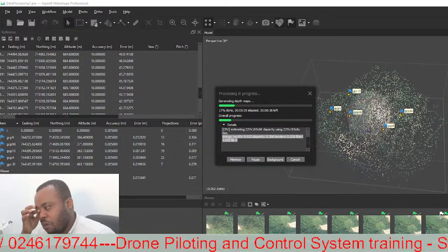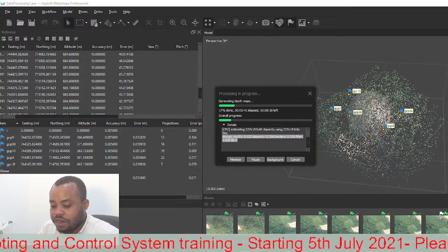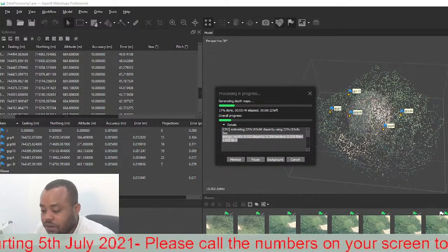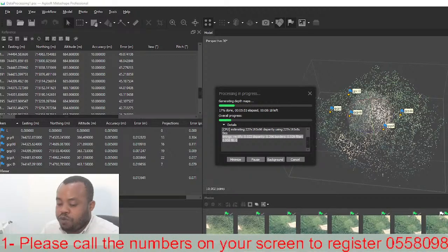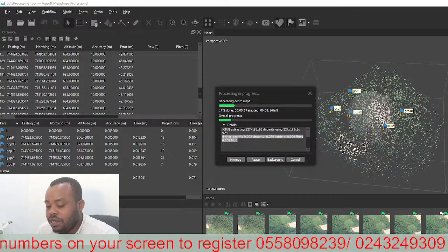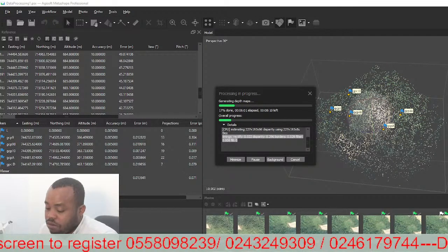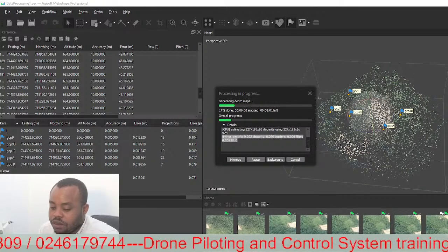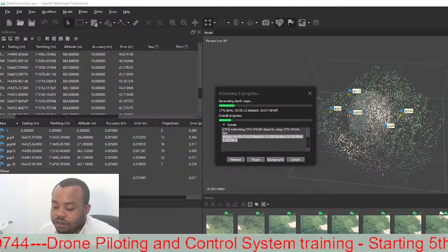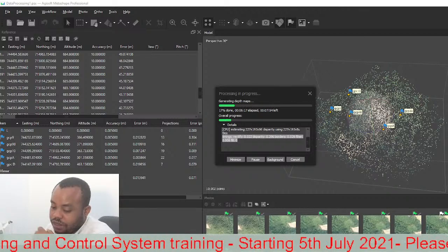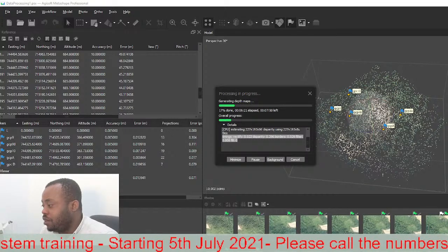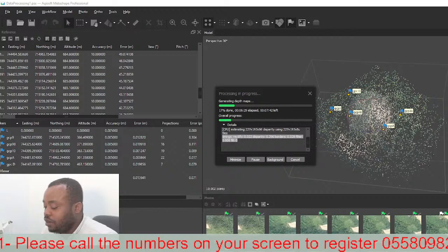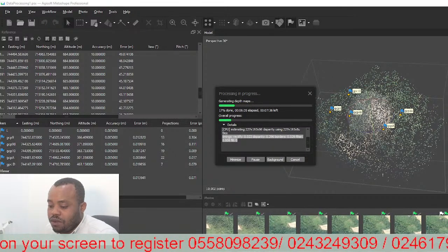Now, when it comes to the graphic card, I will recommend an NVIDIA graphic card. Anything above 6 gig is relatively good for a start. And then for the CPU, I will recommend between 4 to 8 cores, Intel or AMD, 2.0 plus gigahertz. And for the RAM, I will say 16 to 32 gig is good. For the external graphic card or the GPU, NVIDIA is good, AMD is good, but anything above 700 plus CUDA cores would really help. The system that we are using currently has a GTX 1080. That is like the basic configuration. So for a beginner, you can look at that.